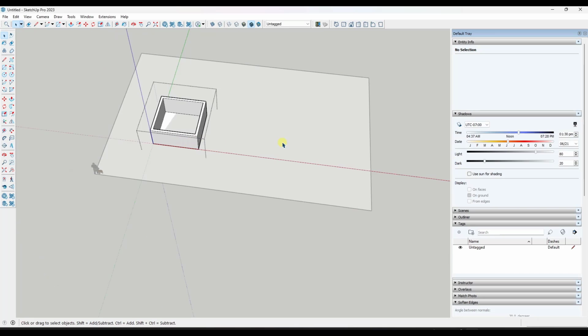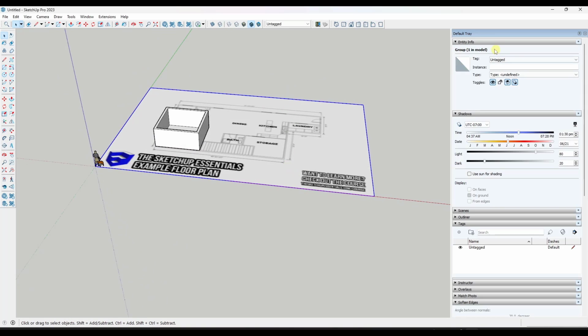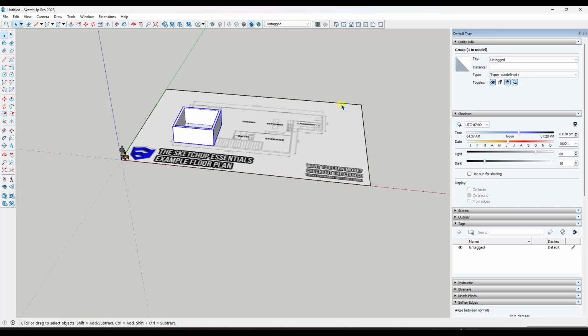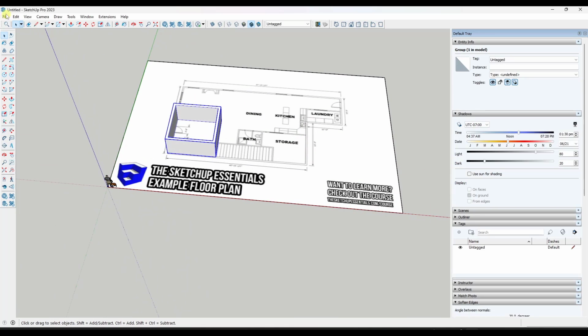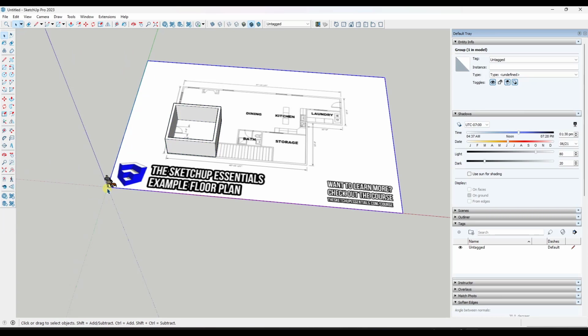This is a weird thing with SketchUp where textures that are applied to objects fade out, right? And when we exploded the image and made it a group, what happened was this is now an object where the texture is going to fade out if we group something. So what I like to do, and I wish there was another way to do this, but I don't think there is, I actually like to re-import a copy of the image that's exactly the same size as this one. When you do that, it's still going to be to scale, but then you're going to have an image object in here rather than a group.